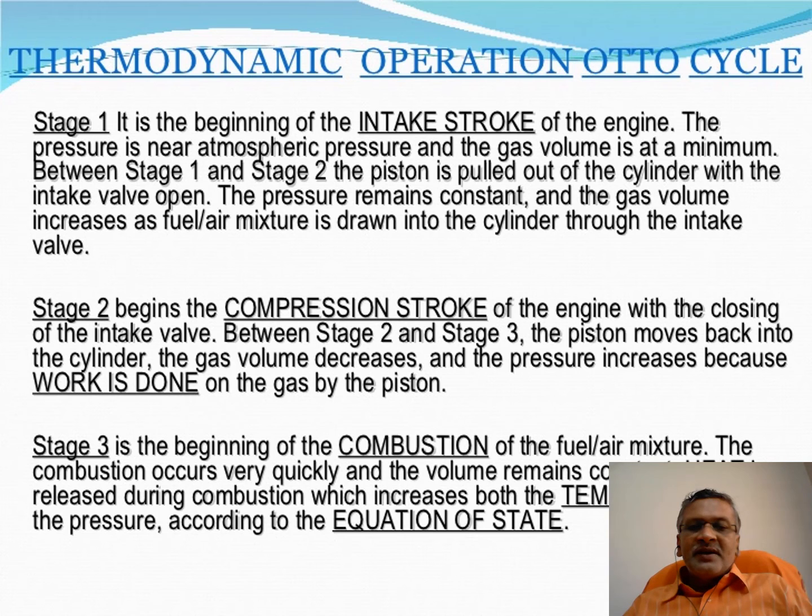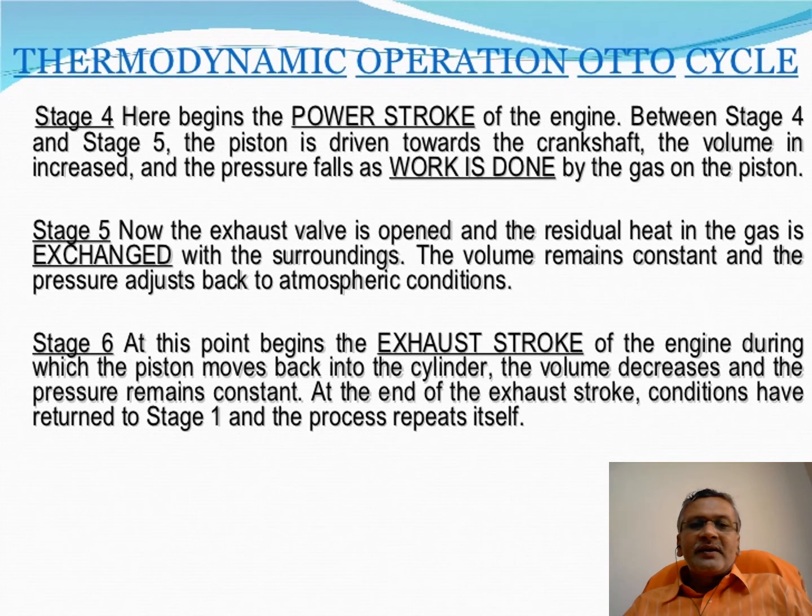Stage 3 is the beginning of the combustion of the fuel and air mixture. The combustion occurs very quickly and the volume remains constant, releasing heat during the combustion, which increases both the temperature and the pressure according to the equation of state.